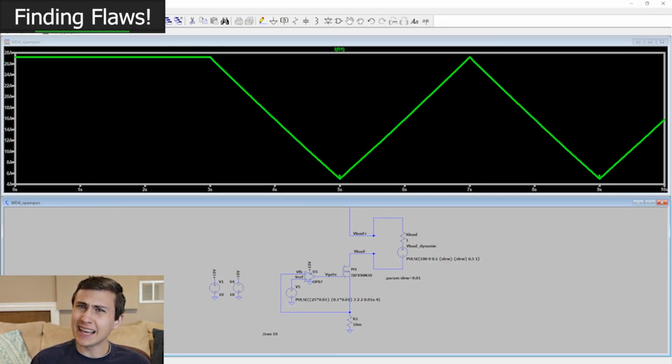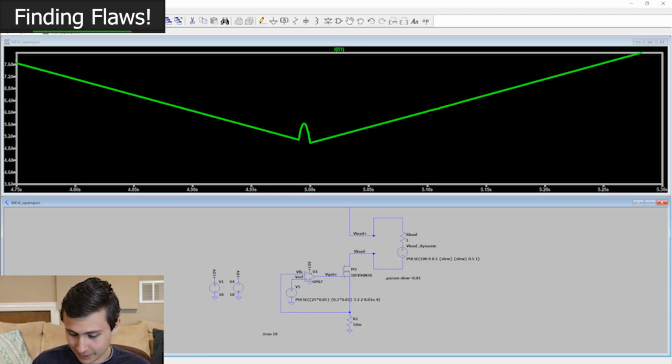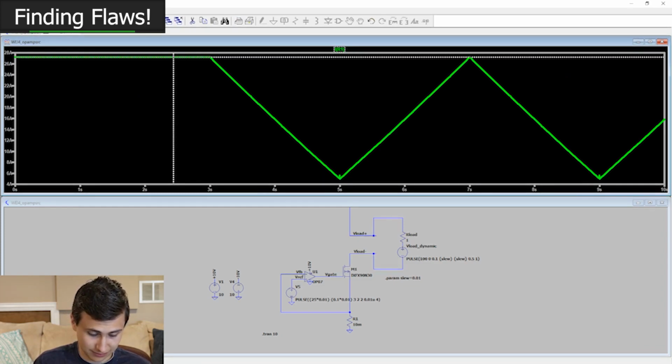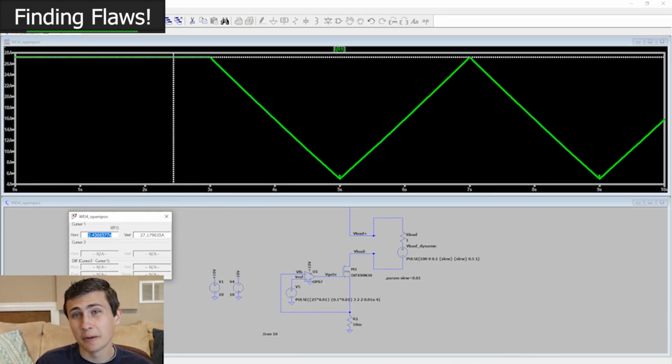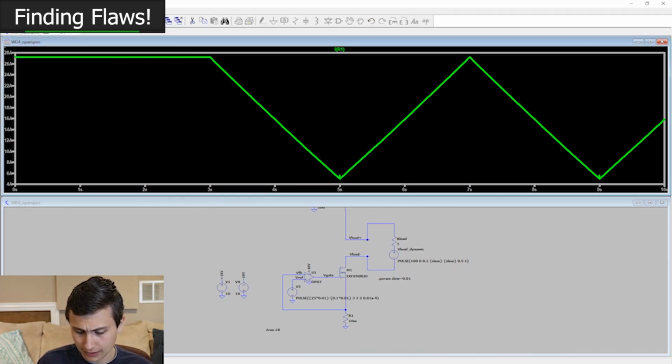Ooh, yeah, we can see that steady state error really ramp up as we get low. Even though we're asking for 0.1 amps, we're getting 5. But on the high end of that, we're asking for 25, and we're getting, what is that? Where's my, oh, there it is on the other monitor. We're asking for 25, and we're getting 27. It's really not that good. And that's kind of what I wanted to highlight today.